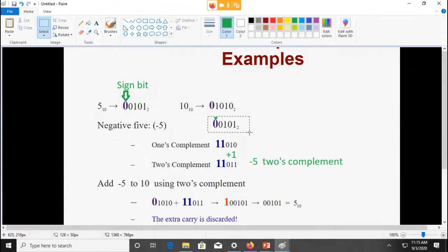So we can do the 1's complement in very, very simple circuitry inside of a computer. And then we can use an adder circuit to add one more to that.